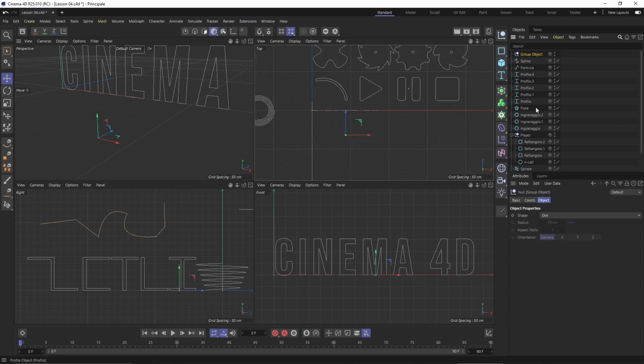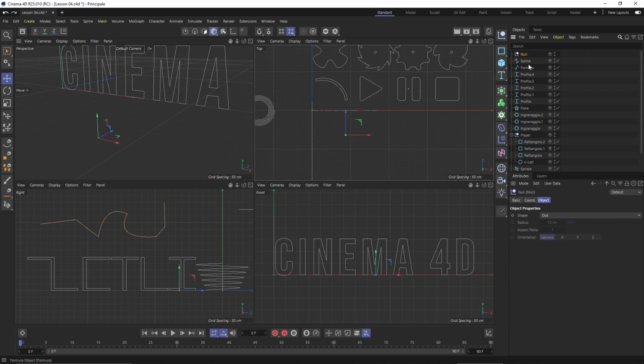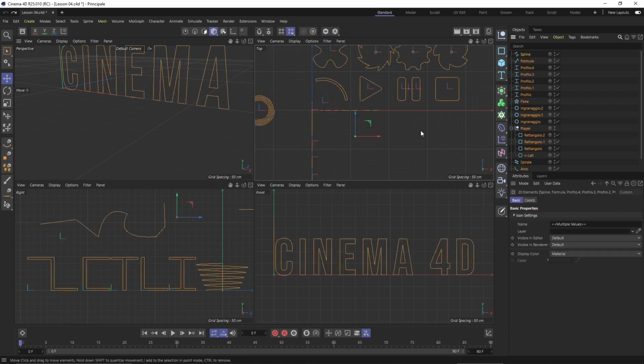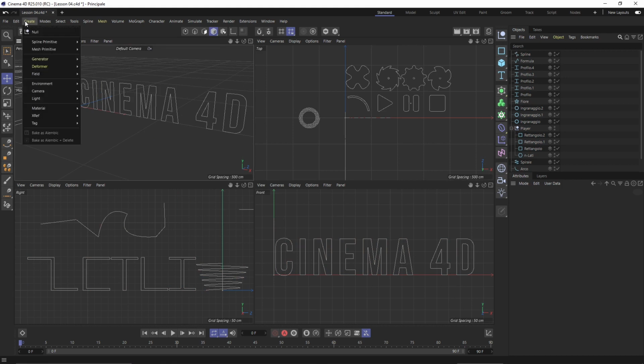Now to place something inside the group or to create hierarchies here from the objects panel, we can select a bunch of objects in the scene and then just drag and drop them inside the null object. And this is going to create a group. Now we're going to make more examples later. Now I'm just going to go back with Ctrl Z. I just wanted to explain to you what the null object is, just to understand how you can use it also later on.